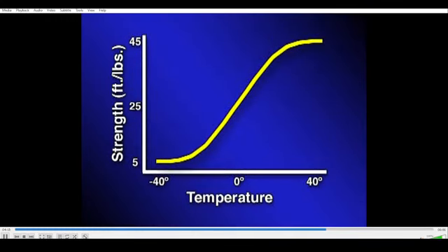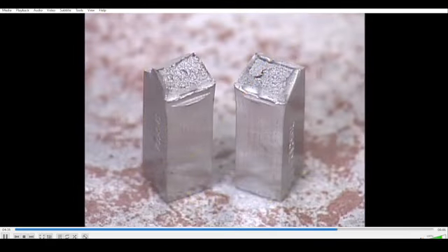The curve developed for carbon steel shows an upper and lower shelf. The lower shelf indicates that the material has lost toughness in this temperature range, while the upper shelf indicates good toughness properties. At lower temperatures, steels normally become more brittle and lose toughness.